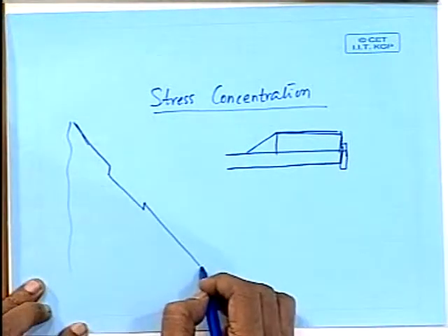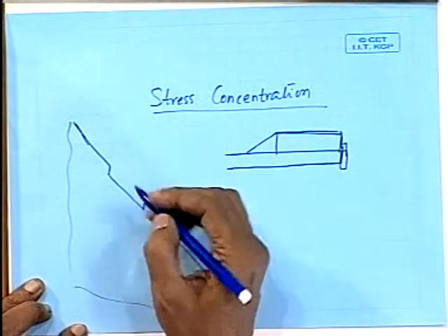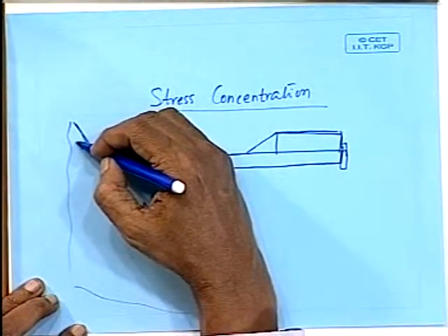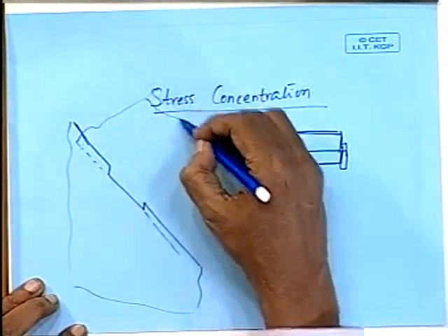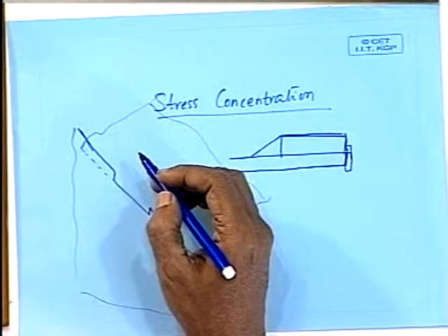So this is the side shell of a ship. This cut is given for a ladder, a gangway ladder, let's say, and this is the upper deck. This is that extra material you take up before the bulwark. You have seen a good ship cross section, I hope. The sheer strake is extended a little bit above the molded lines, and then there is a gap, and then the bulwark plating comes up, right? So this is that extra plate.